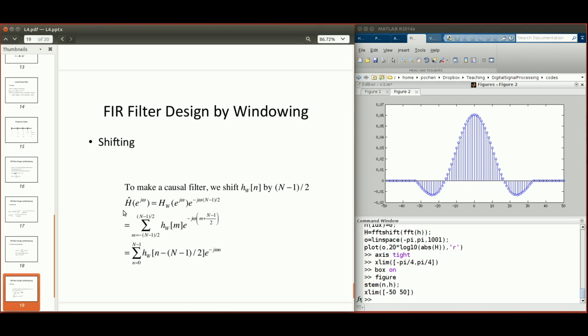And what's going to be the effect in the frequency domain for this particular shift, right? You're basically multiplying big HW with this particular linear phase, right? And that's the amount of the shift, minus (big N minus 1)/2, right? And of course, we can represent big HW by using its time domain representation, small hw, right? So from this step to this step, basically we are just doing a Fourier transform, right? So big HW equals the Fourier transform of small hw, right? e to the minus j omega m. Here I'm actually using the index m, right? And then we can combine the phase together.